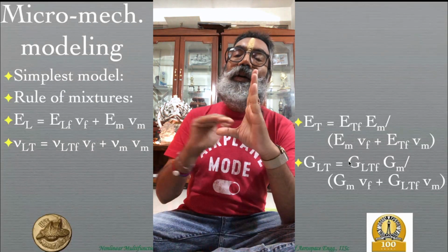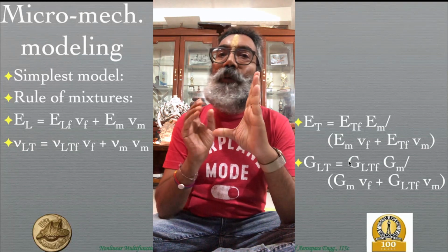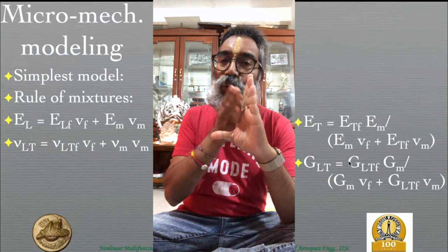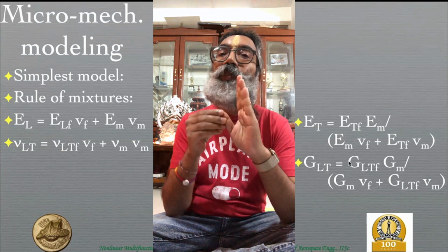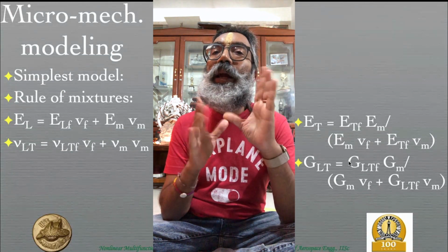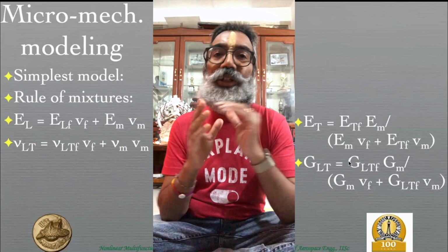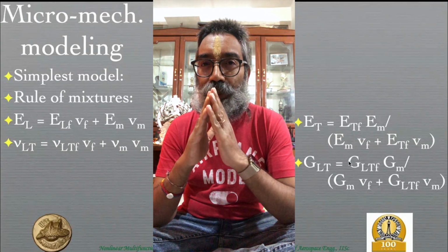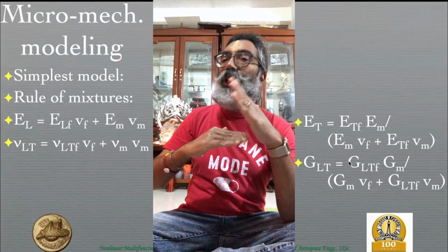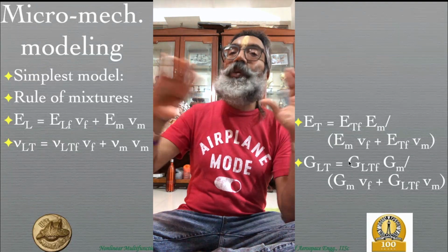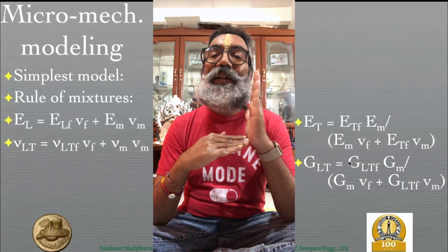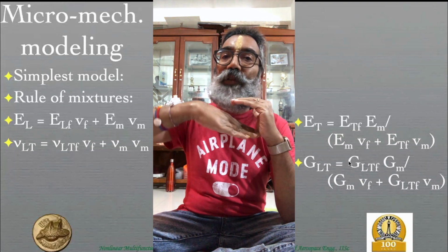And there we are talking about a change in geometry of a 90 degree plane, two planes which are at 90 degrees to each other, as opposed to two planes which are not necessarily orthogonal to each other, and how to relate these two rotations that are happening. And again, rotation can be of two parts. One is the rigid body like rotations, and the other is the shear rotations. So you need to separate these out, and it's much easier to do that when you're dealing with orthogonal coordinate systems like Cartesian rather than with an angular coordinate system or a curvilinear coordinate system.